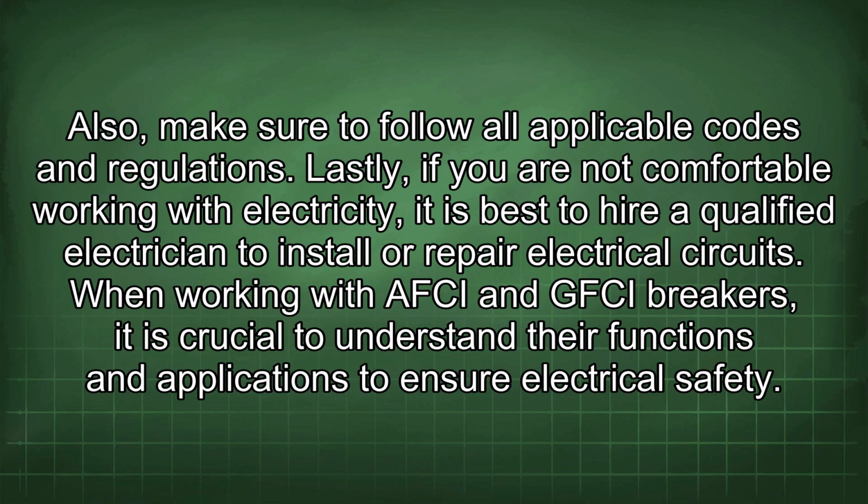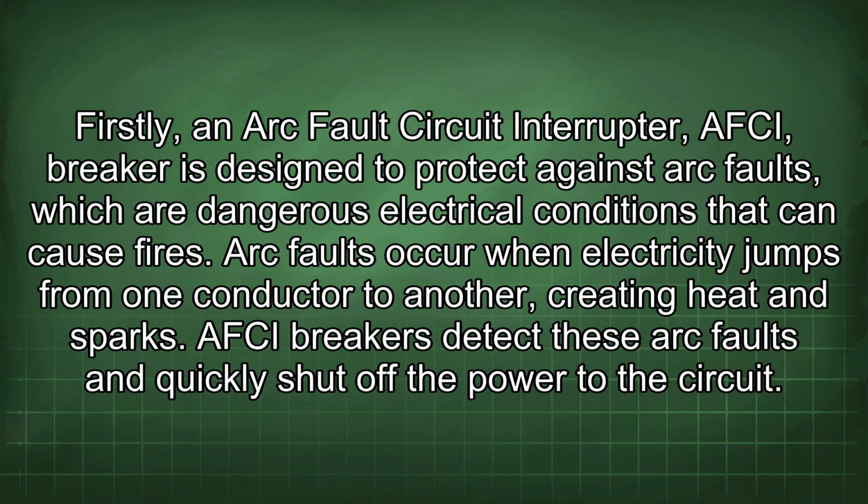When working with AFCI and GFCI breakers, it is crucial to understand their functions and applications to ensure electrical safety. Firstly, an arc fault circuit interrupter, AFCI breaker, is designed to protect against arc faults, which are dangerous electrical conditions that can cause fires. Arc faults occur when electricity jumps from one conductor to another, creating heat and sparks. AFCI breakers detect these arc faults and quickly shut off the power to the circuit.